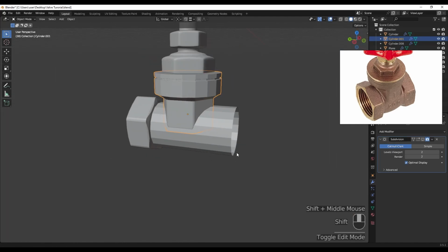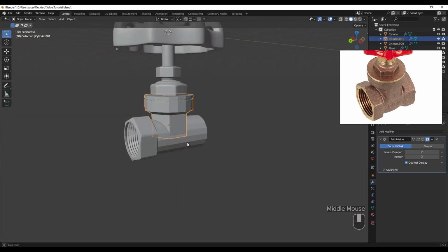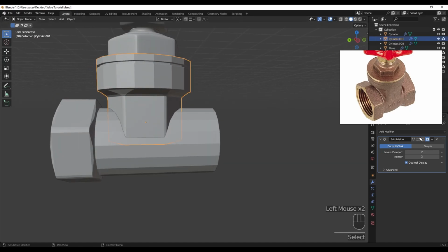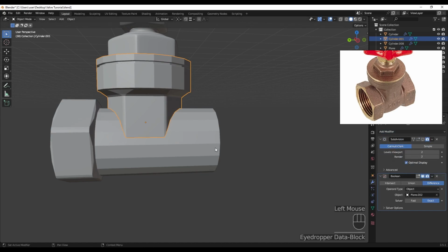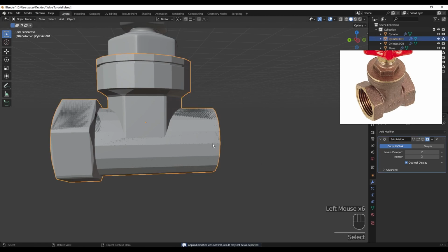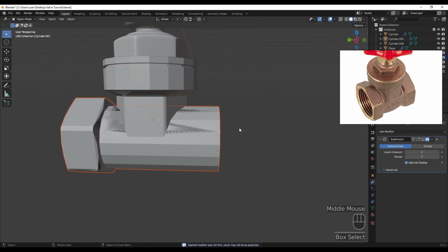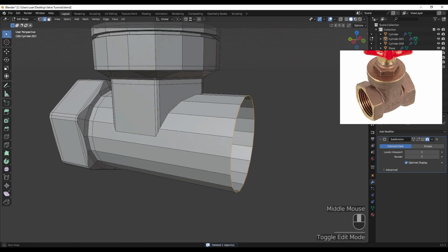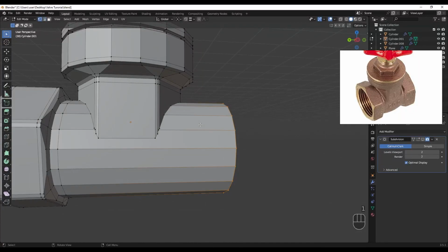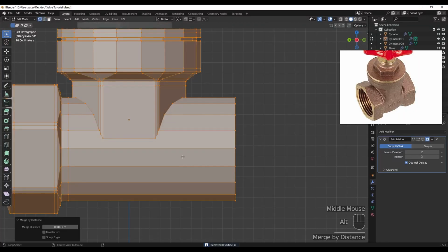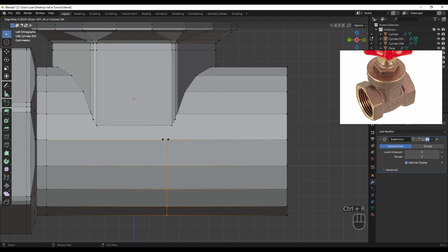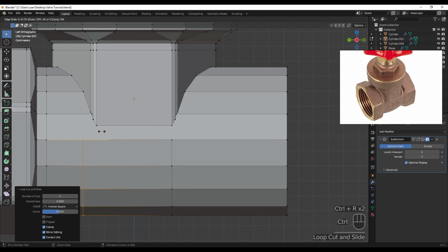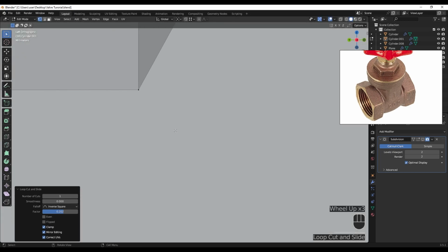And now, right, we can apply the Boolean modifier. So select this one and go to modifiers and select Boolean and select this object and select the union and apply your modifier. And then we need to delete this one and go to edit mode, and let's remove doubles if there's any. I'm going to put the snap to vertex and do an edge loop here and hold control to snap here and here, and let's go closer.